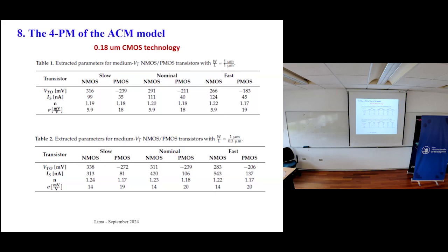You also have a higher limit, because the manufacturers give a higher limit since they don't characterize for very long transistors. So the parameters that they give to you are according to certain dimensions, width and length. So they have a set of parameters depending on the width, depending on the length, okay? They call this binning.